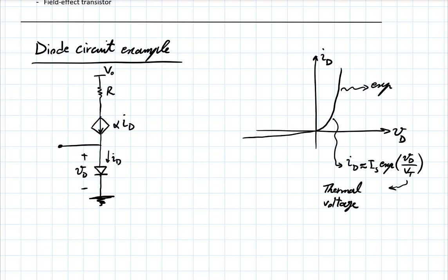Nothing new there. Back when we were talking about this, we said there is also an ideality factor, so n VT, and that n could be 1 or something between 1 and 2 typically. And also there was this exponential minus 1. But if this exponential term starts to grow, that 1 next to it can be neglected.